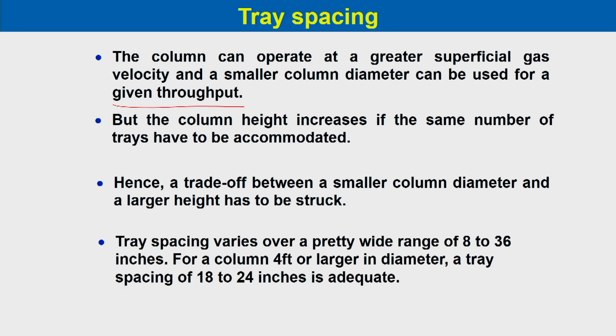The tray spacing varies over a pretty wide range, from 8 to 36 inches. For a column of 4 feet or larger in diameter, a tray spacing of 18 to 24 inches is adequate. So, these are the typical values which are used.